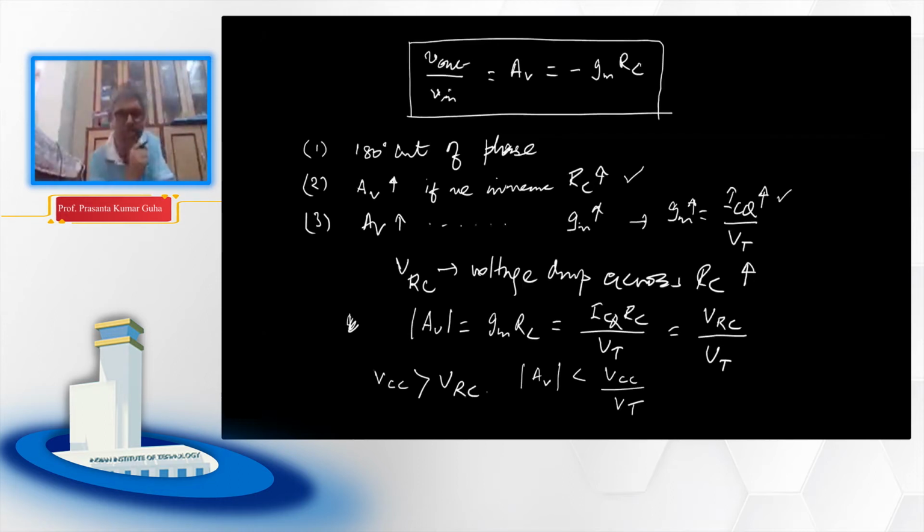In fact, we have to keep this transistor in the forward active mode. So we have to keep in mind that the CB junction should be reverse biased. So we can fine tune this inequality a bit further. Let's for the time being assume that, so this voltage here and this voltage here, so this is your VCB. So VCB has to be reverse biased so that this remains in the forward active mode. Let's think a little bit aggressively and think that say VCE is equal to VBE.